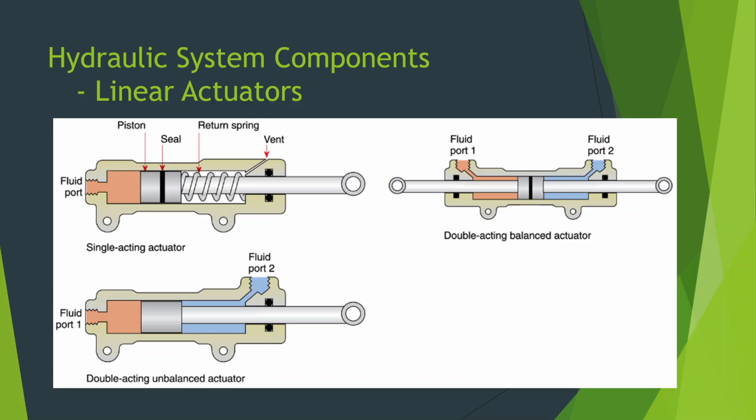The reason for that is we have these seals, the seals that are on the actuator piston, right? They're right next to fluid. The inside of the actuator has fluid on the walls of it, and that allows that seal to move back and forth. But we have to be able to lubricate that interface between the steel components and the rubber seals.